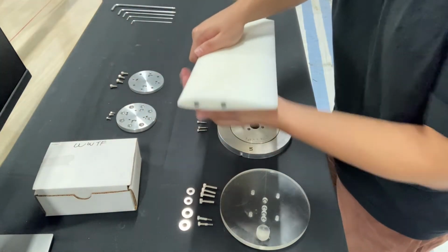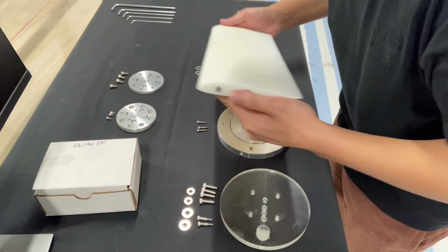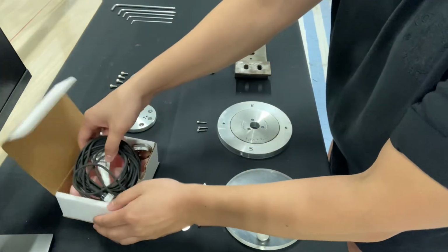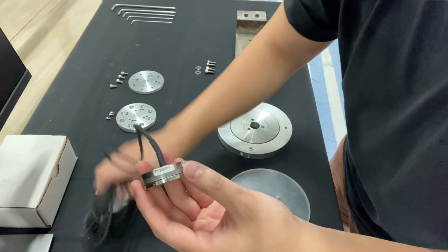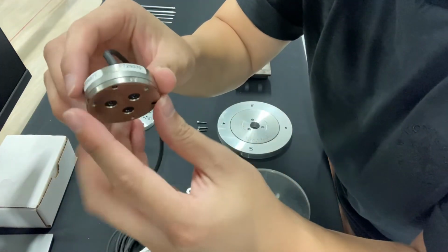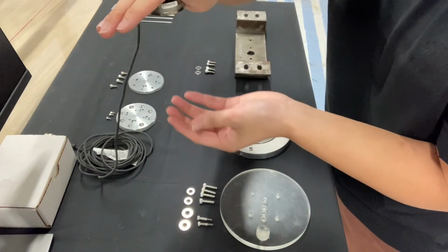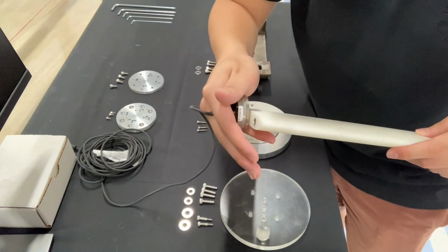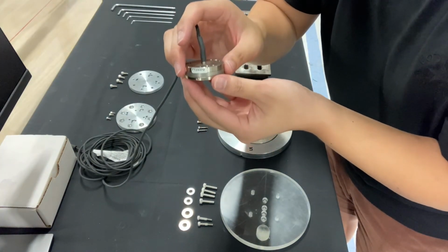Okay, so if we mount this airfoil, the air will be coming in like this, which causes lifting force and drag force. We're going to capture those forces using this load cell right here. But it's expensive, so I'm being careful here. And if you look closer at the load cell, there's a reference axis inscribed. Basically, we're going to fix the top side of the load cell and mount the airfoil on the bottom, like this. And the forces acting on the airfoil will push these two halves of the load cell, creating voltage signals that we read as forces and moments.